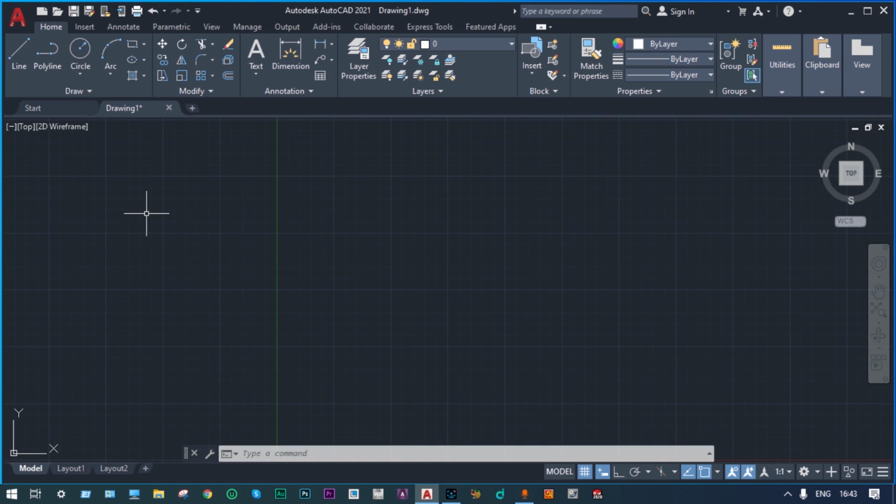As I told you, in engineering drawing, different things are available, like doors and floors. We even have different types of lines, like center line and hidden line, and also hatching lines for sectional views. All these different things we can show in the form of different layers, and we can hide them as per our requirement. To start with layers, we have to open the Layer Properties Manager, or we can write LA for layer. We can do either: click the Layer Properties Manager here, or write LA. So let us click the Layer Properties Manager.